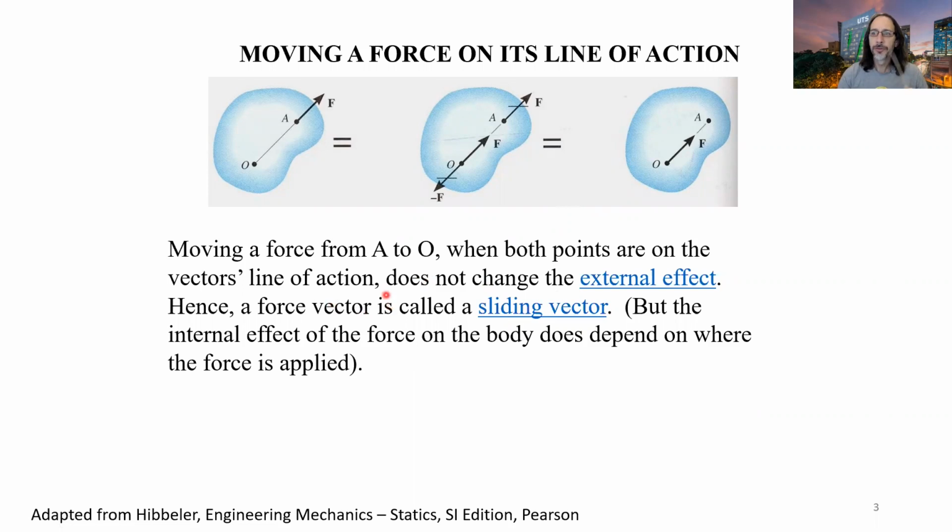Just in terms of the internal effect, so again, if we go back to looking at the internal effects of this, and previously in the previous video, we looked at the fact that a couple is a free vector and we can apply that couple anywhere we like, and it doesn't change the external effect on the body. Okay, but it does change the internal effect. So if you can imagine, if this was an elastic band, for example, if I apply the forces like this, it's going to stretch. Whereas if I apply the force here, you only get a little bit of stretch, and the rest of the elastic band just flops down.